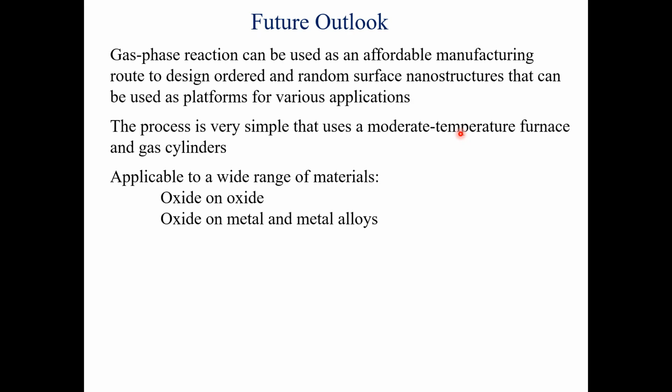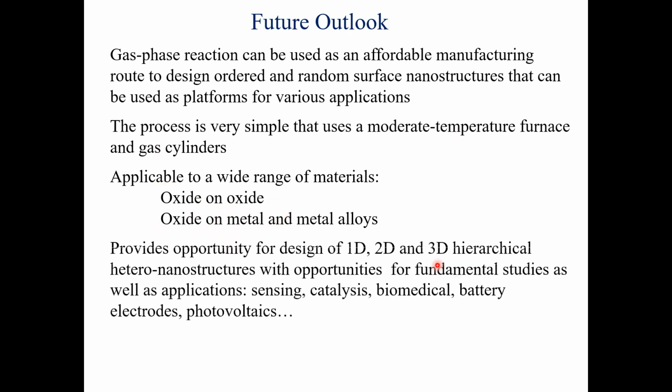Applicable to a wide range of materials, you can do oxide on oxide, you can do oxide on metal alloys. This provides an opportunity for designing 1D, 2D, and 3D hierarchical heteronanostructures with opportunities for fundamental studies as well as application in sensing, catalysis, biomedical, battery electrodes, even photovoltaics.